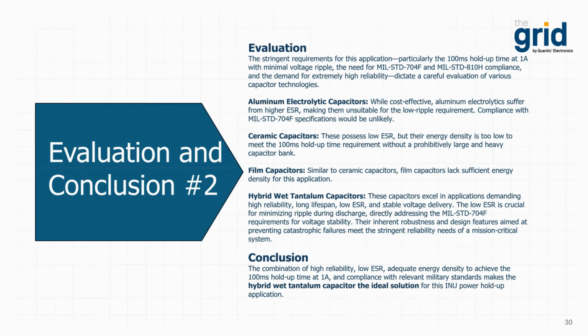Hybrid wet tantalum capacitors, on the other hand, excel in applications demanding high reliability, long life, low ESR, and stable voltage delivery. The low ESR is crucial for minimizing ripple during discharge, directly addressing the MIL-STD-704F requirements for voltage stability. Their superior performance over a wide temperature range aligns perfectly with the specified operational conditions. Their inherent robustness and design features aimed at preventing catastrophic failure meet the stringent reliability needs of a mission-critical system.